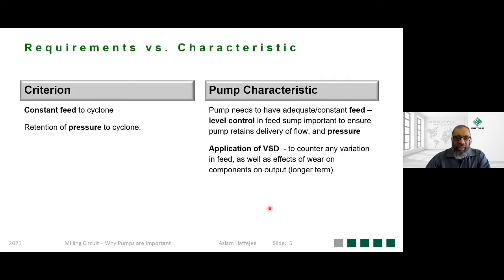One other important factor is the use of VSDs with the pump, variable speed drives. This is to counter any variation you might encounter in the feed or if your density changes, etc. But there's also a different aspect where you might find wear on the pump itself, and the VSD is also effective in helping with that.